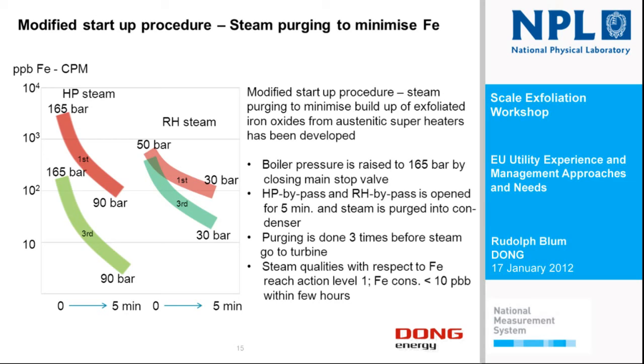So we developed a modified startup procedure where we purge the superheater and reheater three times to get rid of the exfoliated material which has probably formed during shutdown.